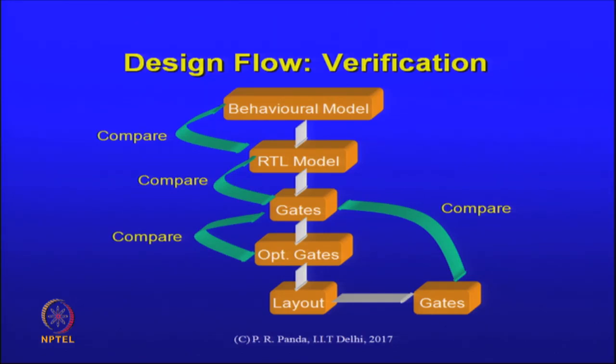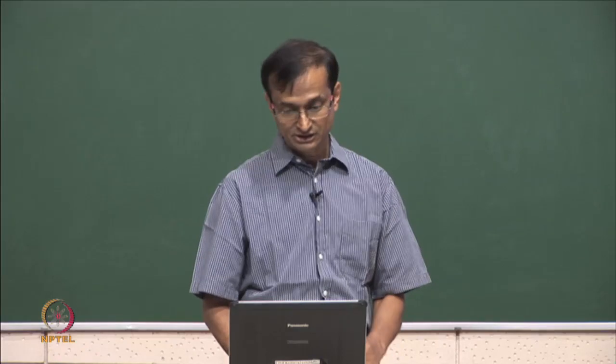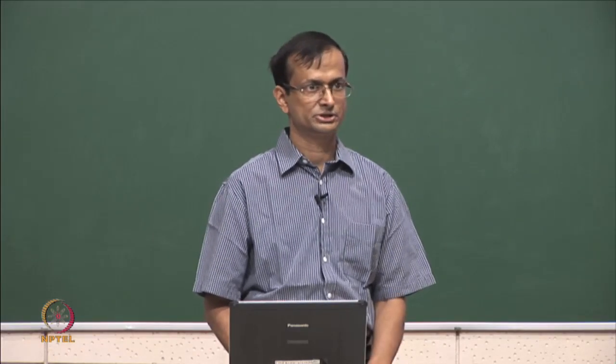Even in the forward step, the synthesis, not all of those steps are necessarily automatic. Some of that synthesis is just happening in our minds. For example, going from a behavioral level into an RTL level forms what we indicated as behavioral synthesis. But all of that could well be just steps the designer goes through and comes up with, and enters the design directly at an RTL level of abstraction.